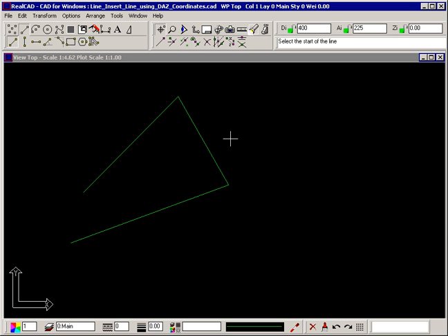The little green padlocks on the coordinates bar are used to lock one or more of the coordinates to help you draw. A green padlock means the coordinate is unlocked. A red padlock means the coordinate is locked, although the actual images change as well, so they look locked or unlocked. For example, locking the D coordinate constrains any lines drawn to the length specified or multiples of that length.